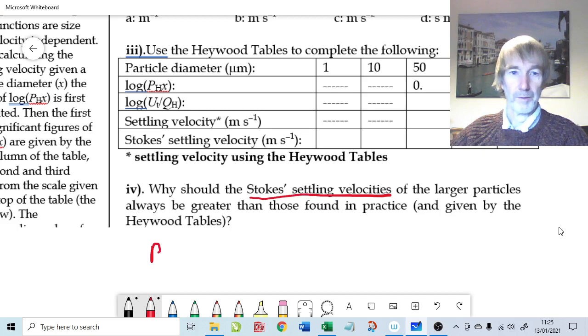And the particle Reynolds number is quite simple. We'll use a prime to differentiate particle Reynolds number from flow Reynolds number. Every chemical engineer remembers Reynolds number to be d u rho over mu. Well, the characteristic linear dimension here is of course going to be the particle diameter rather than the pipe diameter. Rho is of course still there, d u rho over mu. So we also need a velocity, and over mu, the coefficient of dynamic viscosity.